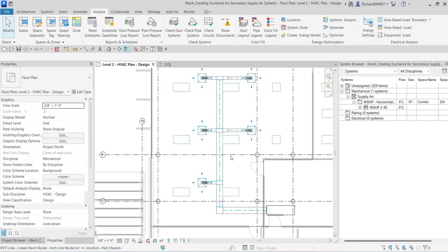So that's why it's also important to specify the height of your duct. What you do is either relocate the system components manually, select a different layout solution, or manually modify the ductwork. So remember to always check the duct connectivity after modification.